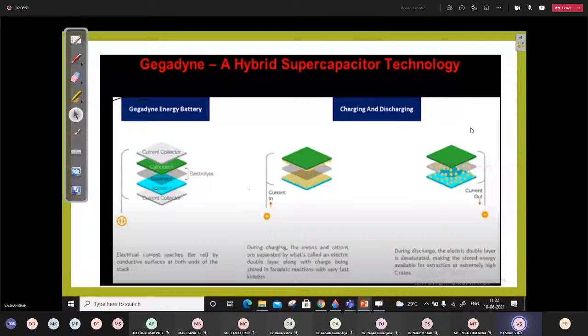And this is our own developed driving cycle to test the vehicle operation. So we provide these driving cycles as the input, and this provides information about the driver nature, road conditions, and traffic conditions, along with the speed variation with respect to time.